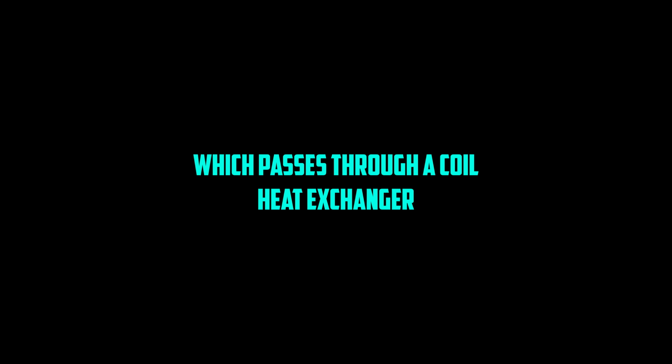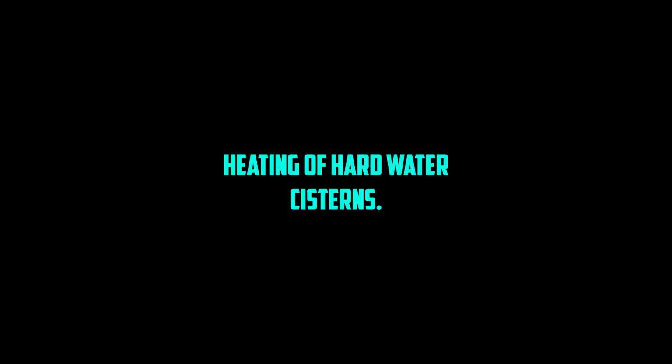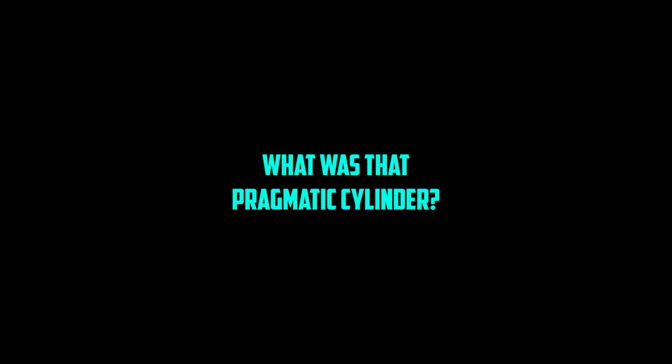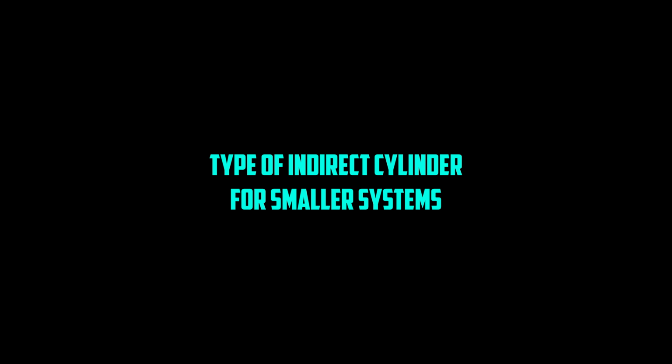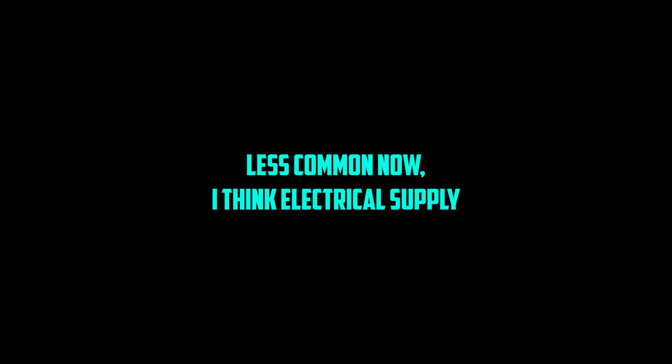Hot water systems. Indirect seems standard now, especially with central heating or in hard water areas. The boiler heats a primary circuit which passes through a coil, heat exchanger, inside the hot water cylinder. This heats the stored domestic water indirectly, preventing scale buildup from direct heating of hard water. Cisterns feeding these systems need insulation against freezing. What was that Primatic cylinder? A clever, simpler type of indirect cylinder for smaller systems, uses internal baffles and airlocks to keep the primary and stored water separate within the same tank, saving some pipework. Less common now, I think.